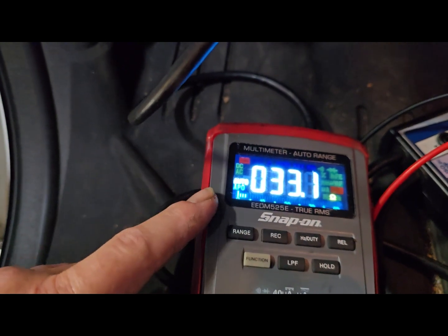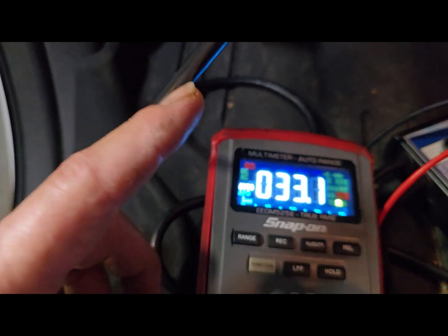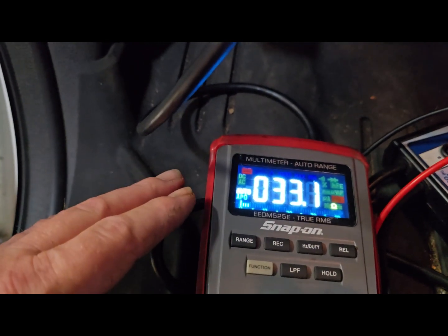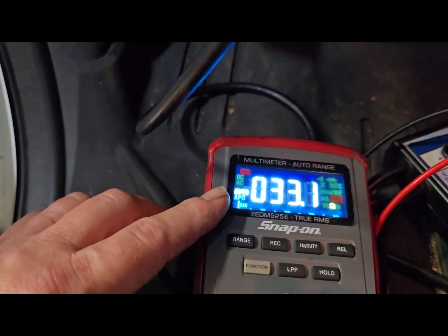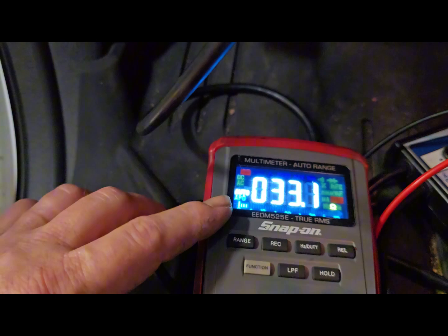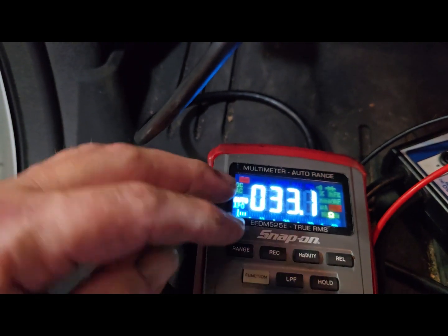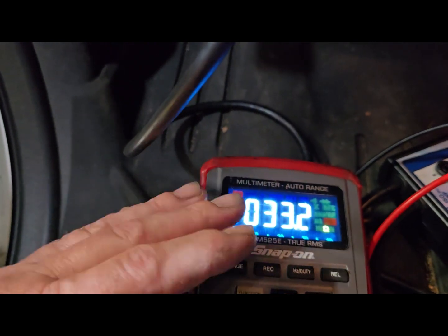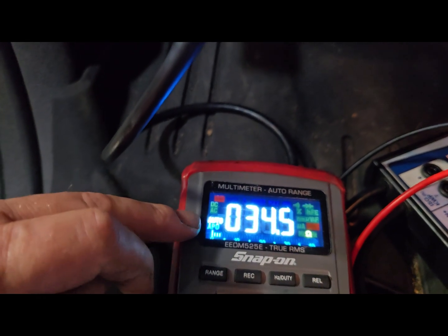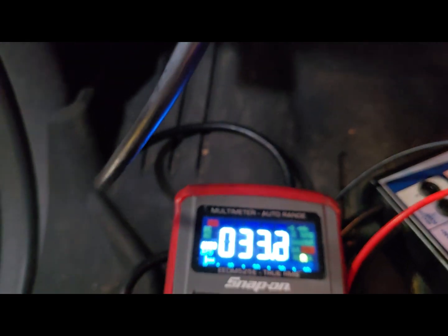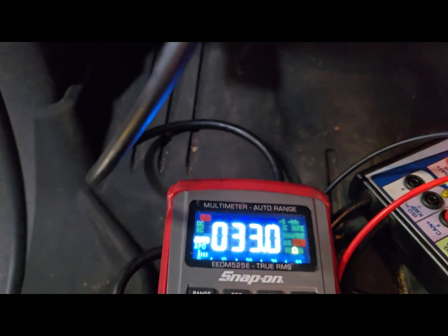But before I disconnected anything, when I first got to the vehicle, I plugged in here, and I had 60 ohms. As soon as I turn the key on and the IPC drops, this goes to mega ohms, thousands of ohms. It jumps all over the place. We have extremely high resistance. So now you can see that we have 33 ohms, supposed to have 60.